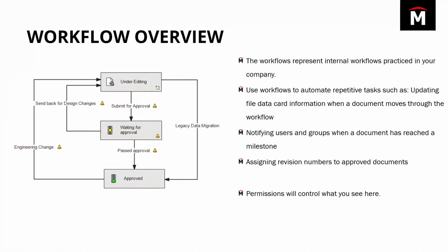The next thing we're going to get into is the workflow. Now, the workflow, I like to say that the workflow is really the backbone of the PDM system. So when you're implementing PDM, this is an area that you give a lot of consideration to. And this is really where we gain a lot of intelligence and efficiency from the software itself. Think of the workflow as like being an electronic version of your procedure manual. If your procedure manual states that your documents must have a set of checks and balances before being released to manufacturing, then the workflow that you configure, or that we configure for you, should be configured to electronically reflect that approval process.